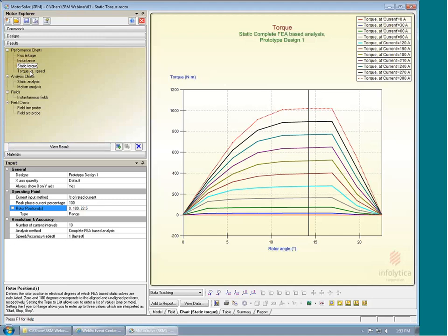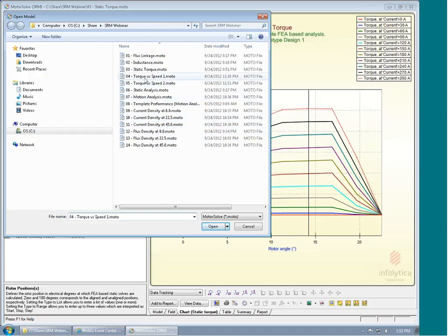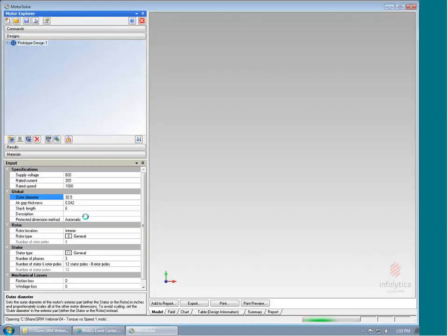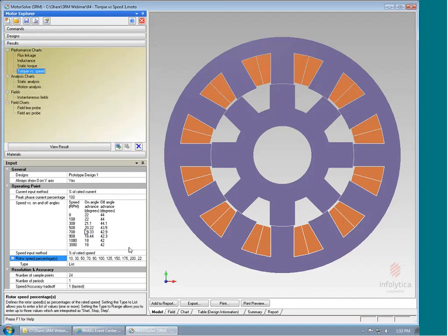So now let's actually look at the torque speed curve, or the response of the torque speed curve for this machine. And in this setup, there's another feature which is very, very important, and that is that you can actually enter the firing angles. A very important aspect of the switched reluctance machine is to be able to control the on angle and the off angle for the firing for each of the phases as the machine rotates. This is what might control motoring or generating, for instance.